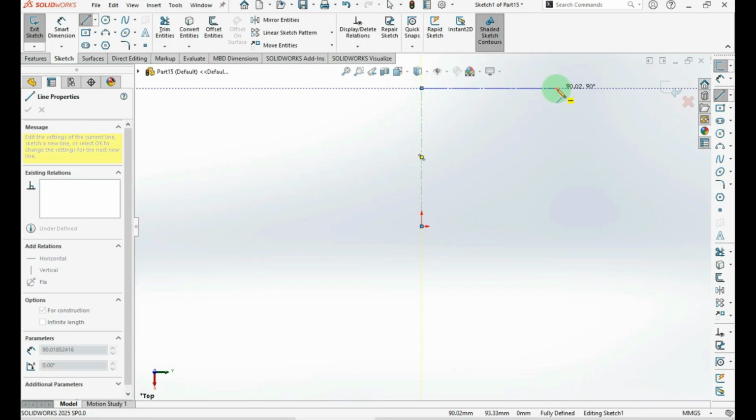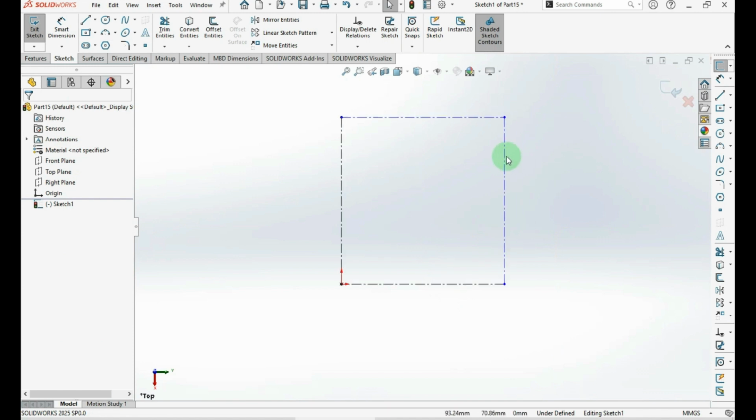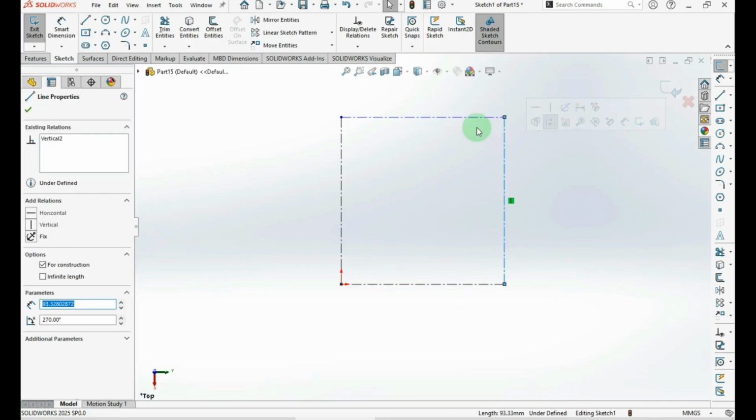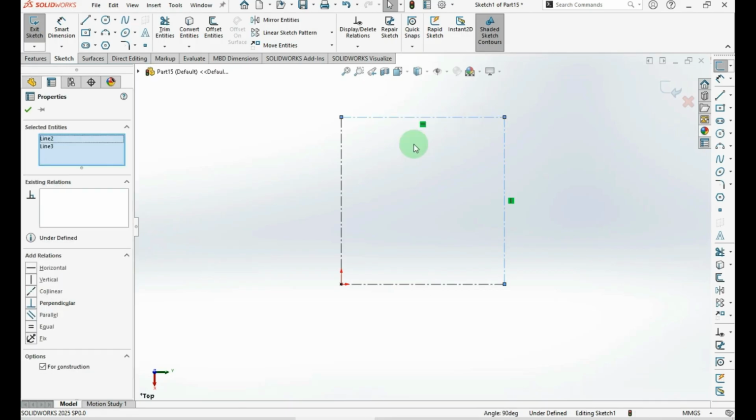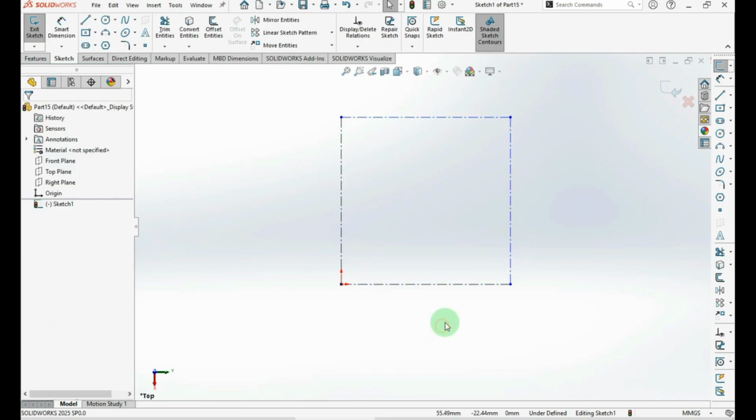Okay. I create the borders from the sketch that I designed on the paper. I select this line, press Ctrl, and select all the other lines as well. Now you see some options here that SolidWorks suggested for us, including some tools, dimensions, and some mates. I select the equal, make them equal together. Now they are all of equal length.